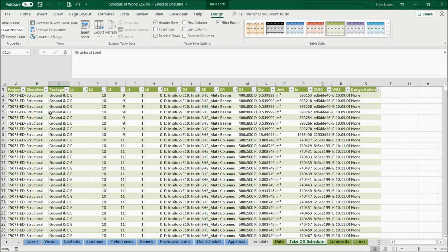So this method is not just looking at the project, where you would have several models in a single building and then they would need to be federated, so they may have different names. You may have a building split into different blocks. Again, this would be shown up in this project name. The discipline can also be changed, which should be part of the project. We have our packages, and then we have our different single items, and we have our GUID and ID within that project. This will be completely unique, and that will be unique to this project.